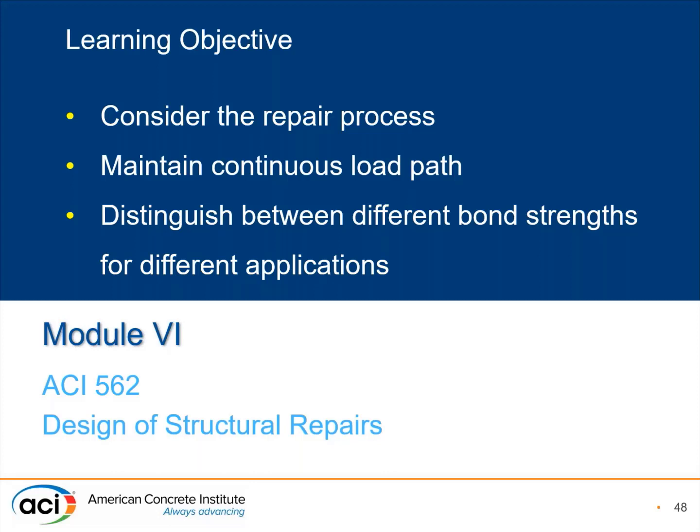When we're looking at conventional repairs, we're removing concrete and putting new concrete in its place, and the efficacy of that repair is strongly impacted by how well strength compatibility is established between those areas, how strong that bond is, how to achieve that strong bond, what bond strengths are important, and how to evaluate the need for testing or the use of interface reinforcement.